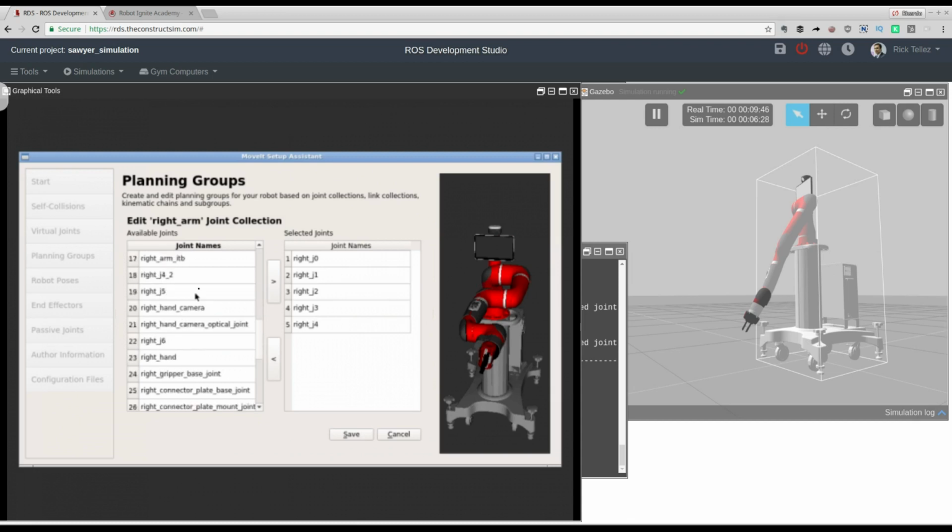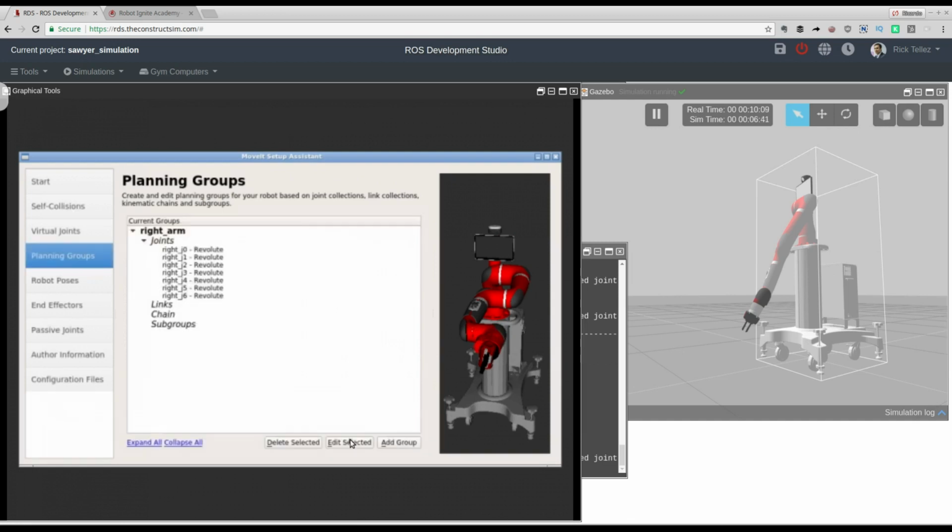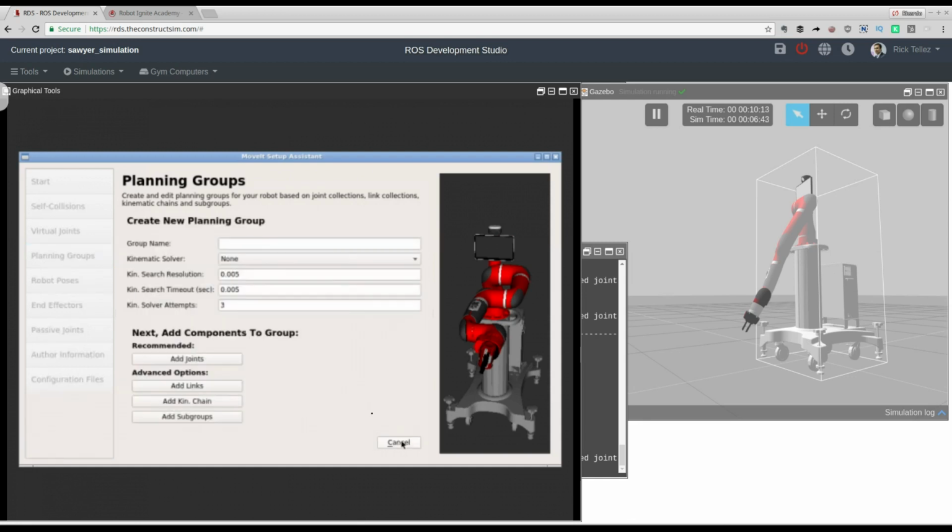And instead of opening the whole URDF and following, which is also interesting to do, but okay, now we go fast. So J5, that is the one here. So select that there, and then J6 that we have there. And now we have all the joints that correspond to the arm. Okay, let's save it. Now we are going to create an extra group that is for the gripper.